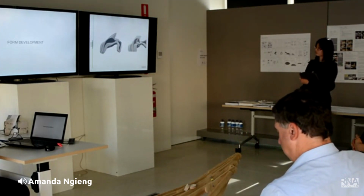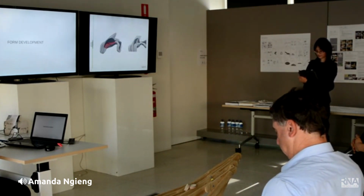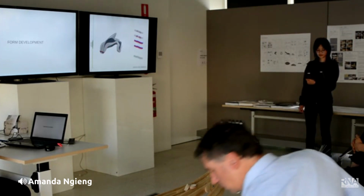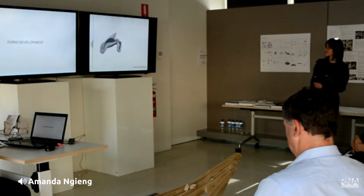The roof was too low, providing not enough headroom. Due to material length limitation, we cannot raise the roof further, so the shape of the seat was adjusted instead. To reduce the number of small pieces at the ends, the pieces were merged together. Additional bracings were added to ensure stability.